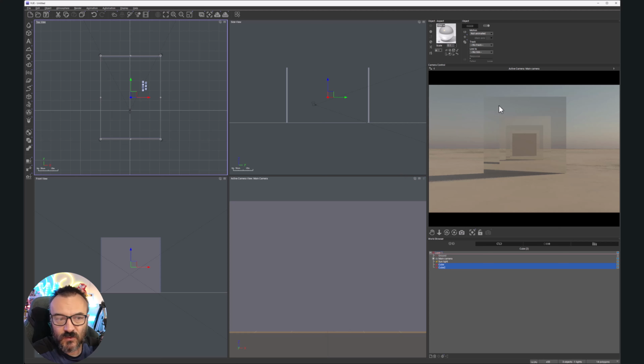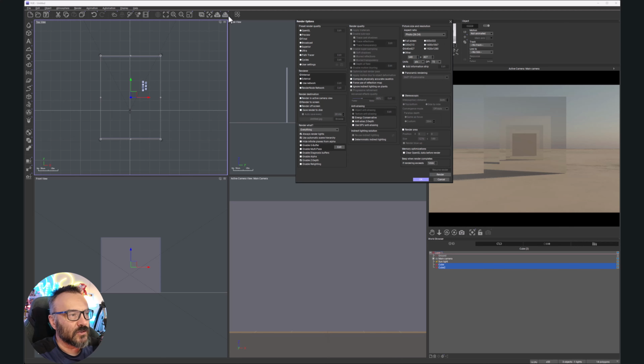Remember before it wasn't. We have another reflection, another, and right here, look, we have this gray box. And the gray box, it's a default whatever material was, where no reflection is applied. To change this, we need to change how many times the light ray can go back and forward and render. And you can do this in multiple ways depending on what material we're using inside the view. Let's show one of them.